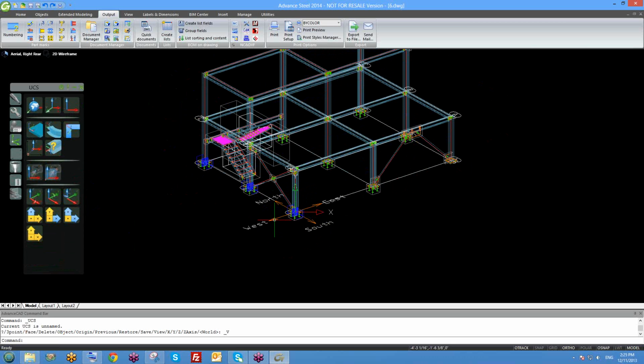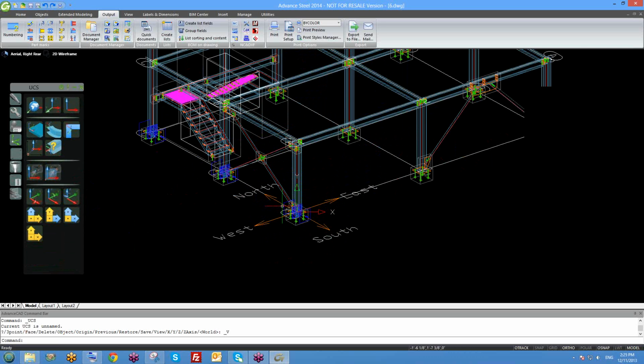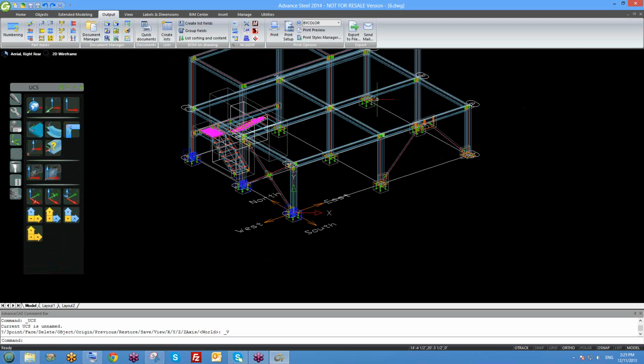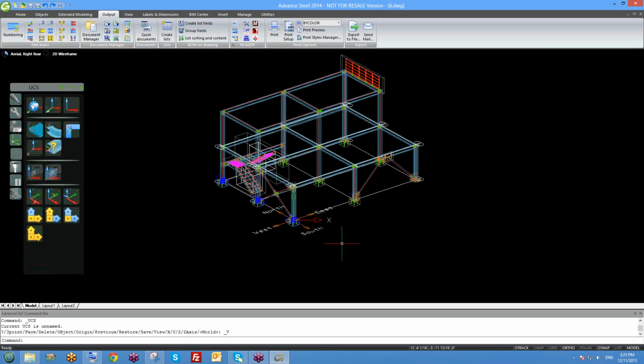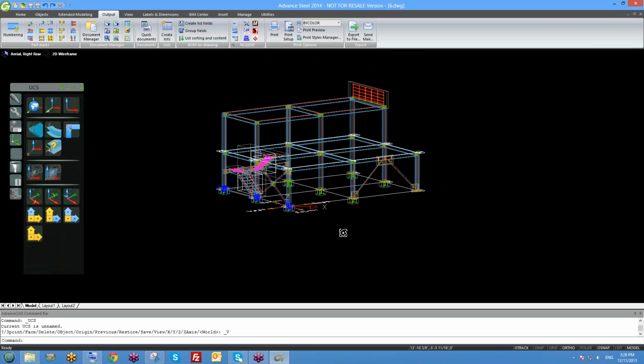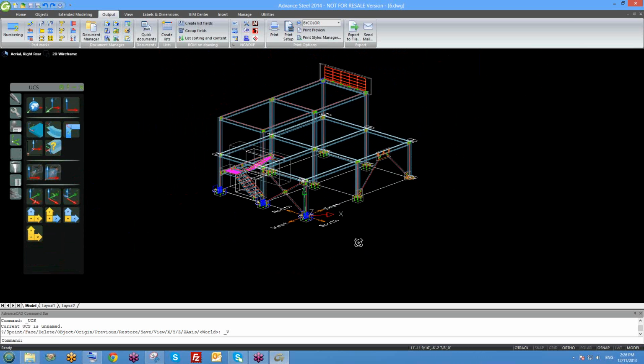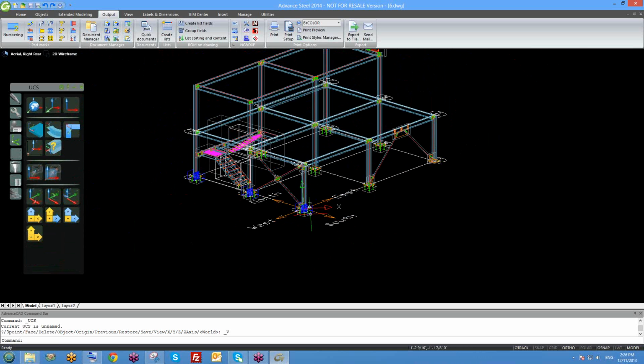No matter what the location of your UCS is, if you place your UCS at one of the corners of your model, you're fine. Now just do an orbit to get your desired view, because this view is the one you're going to get.